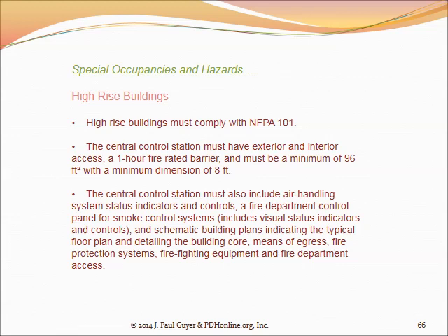And then, of course, in the stairwell typically is the fire sprinkler riser. This is the vertical pipe that contains the water supply that the firefighter connects to with his hose at the floor when he gets to the floor where the fire is located.